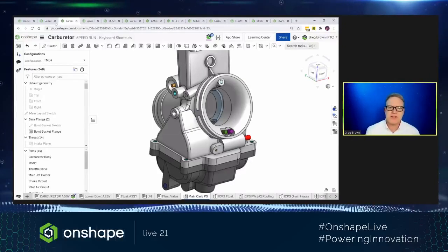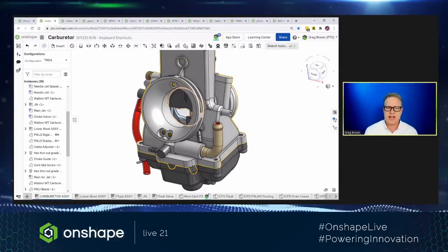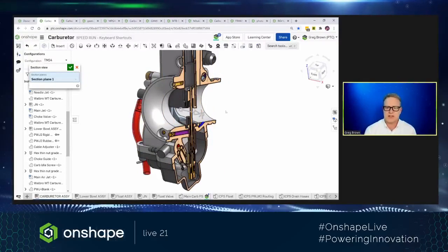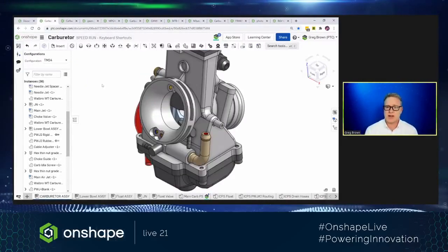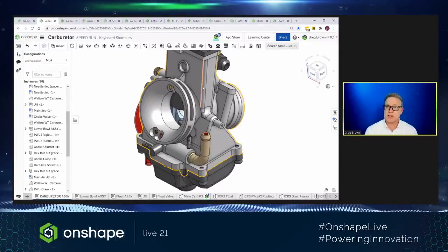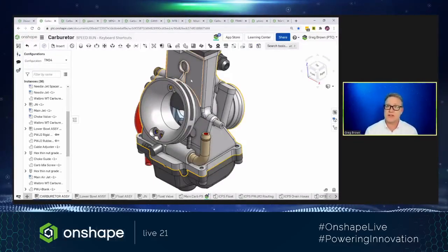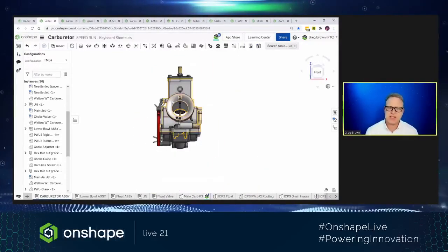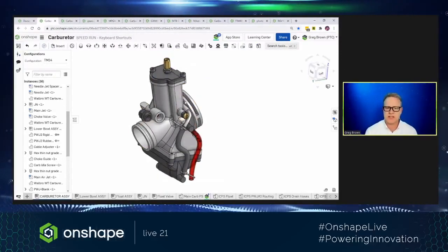Also, did you know that in many cases, there's no need to actually select an object to carry out a task? You just hover over the object, and then there are numerous keyboard shortcuts, such as create sections, things with visibilities. Also another one with translucency, you hover, Shift T, or hover and N, give it a few normal. Each time saves a few clicks, but it adds up over the course of a whole project.